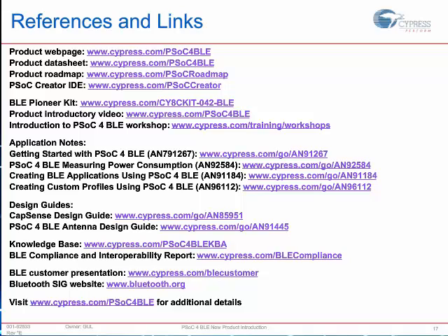Is the PRoC BLE module certified already, or does it have to go through certification if you're going to be using it? Yes, so the PRoC BLE module, as I showed in slide 21, I believe, has full global certification from all of the regulatory authorities like FCC, CE, and JRL, and it has pre-qualification from the Bluetooth SIG. So it's fully certified by regulatory authorities for its RF portion, its wireless portion. It's fully qualified by the Bluetooth SIG for its Bluetooth compliance and compatibility.